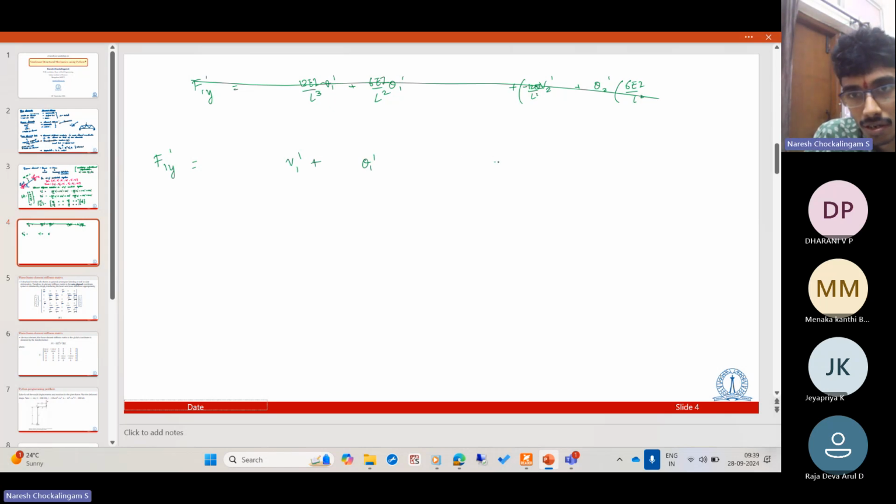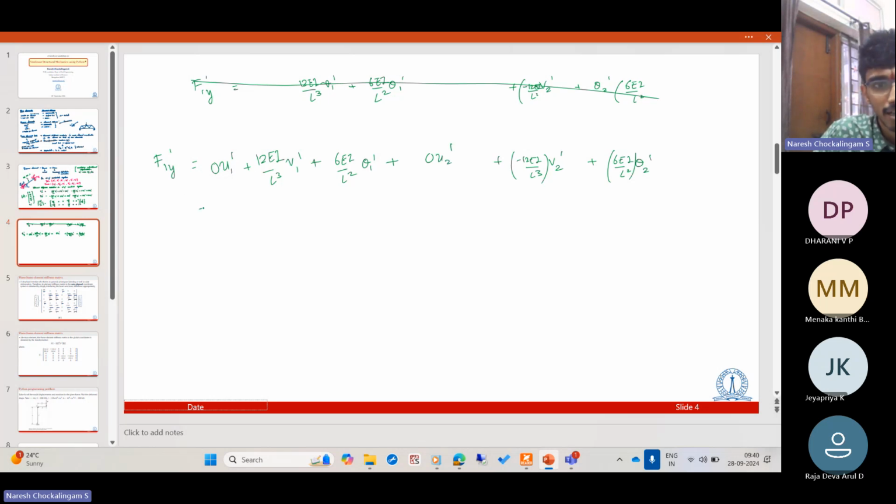Theta 1 dash plus something times V2 dash plus something times theta 2 dash. So this is 12 EI by L cube, 6 EI by L square, minus 12 EI by L cube and 6 EI by L square. Again, you can fill it up with 0 coefficients, so you can add a 0 u1 dash and 0 u2 dash. So this is a beam equation and it depends only on...